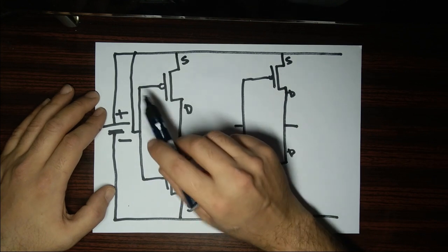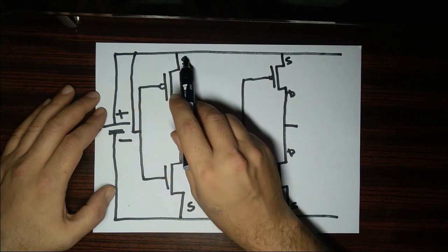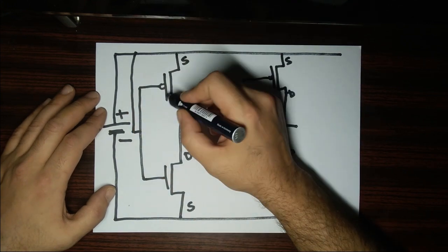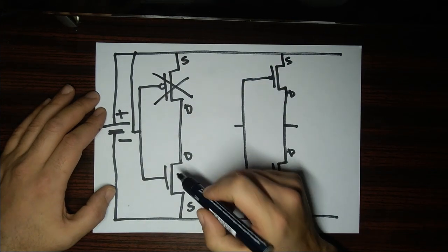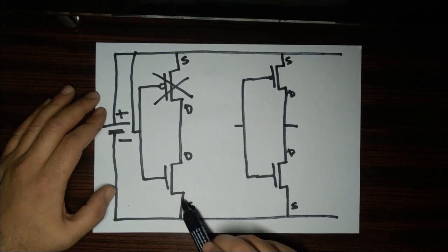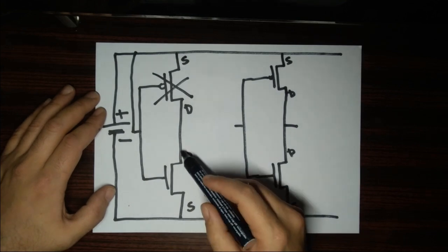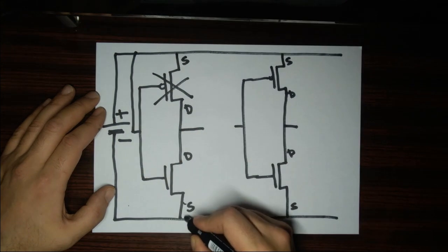Remember, the gate needs a negative voltage difference to its source to turn on, and we currently have 0. So it is acting as an insulator. The N-type, however, is on, since there is a positive voltage bias on its gate compared to its source pin, and is now acting as a conductor, or a wire if you like, effectively connecting this point to the ground.